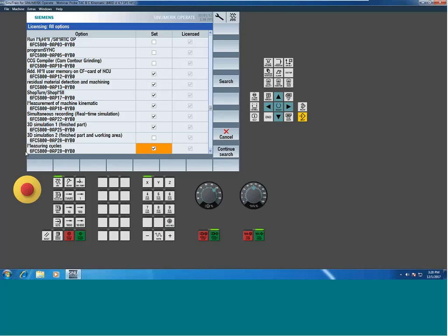Keith says, how do I use the probe to select one of 4 programs? Measuring in Z, look for one of the Z heights and select the part program according to the measurement. Oh, okay. Usually what I would do there is I would have a main program, and I would have some simple logic statements set up. So I would come down, I would take my measurement, I would then do an if-then or some type of logic statement. Check out that variable webinar program I did. I get into some of those logic statements.